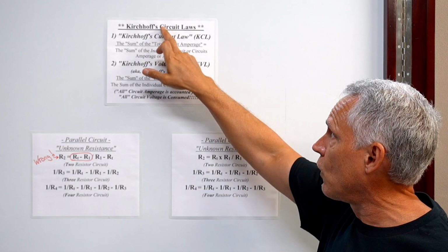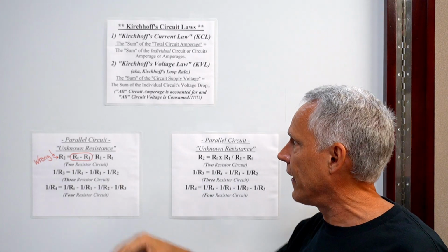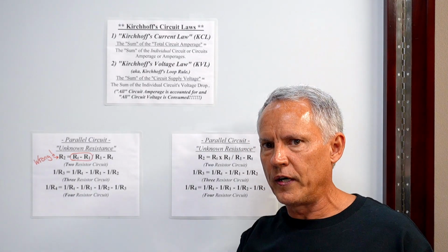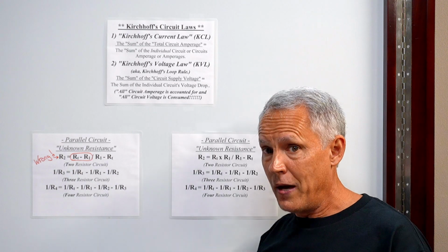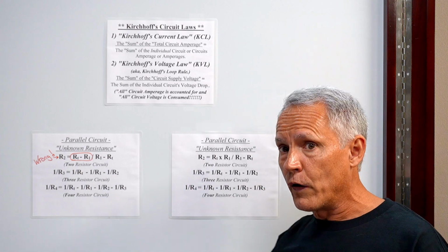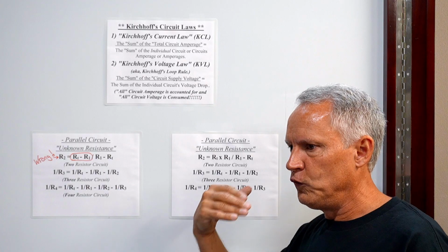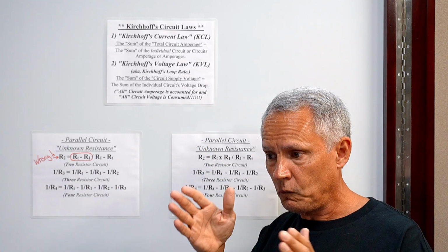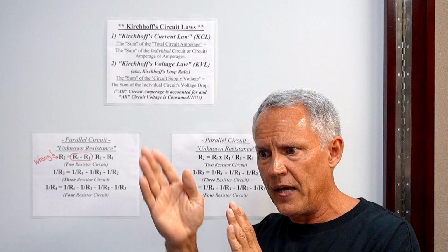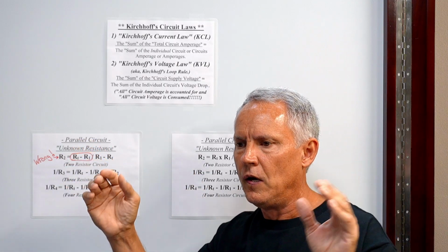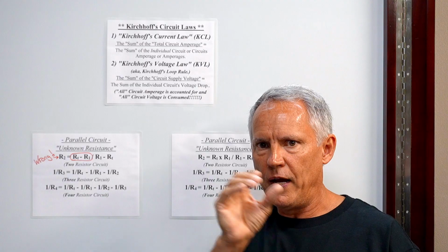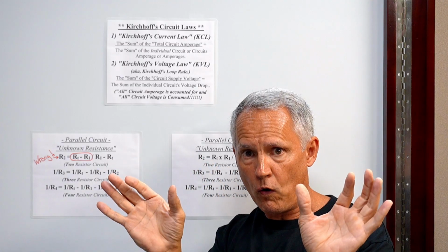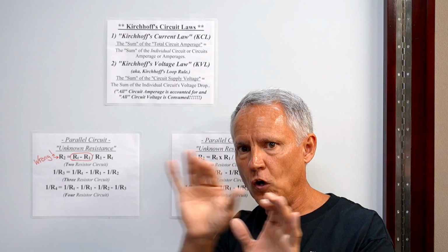So let's just say that Kirchhoff's circuit laws are saying that if, for example, a circuit has 12 amps, a known value, you've measured it as 12 amps or you've calculated it at 12 amps, as you break down the circuit, whether it be series parallel or parallel, into a single leg or multiple branches, the individual values for amperage, let's say 4 on this leg, 4 on that leg, and 4 on this leg, or 4 on all 3 branches, that'd be a total of 12.